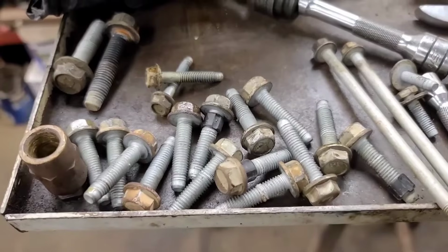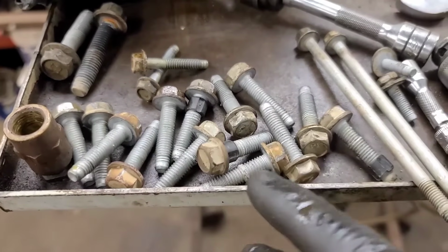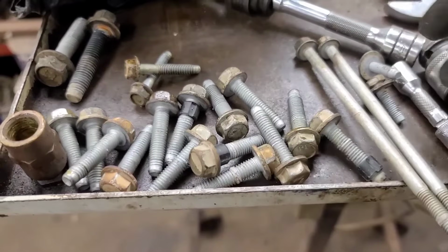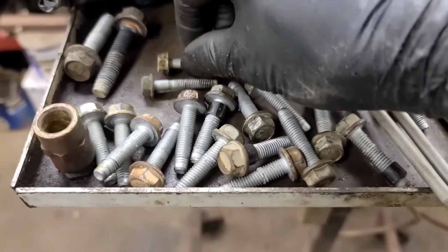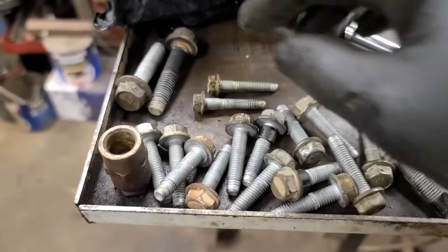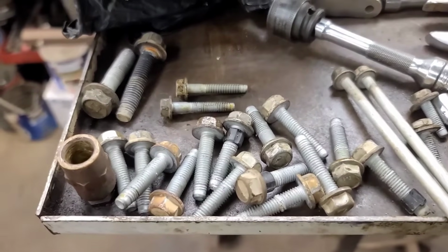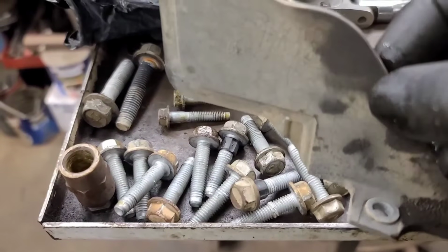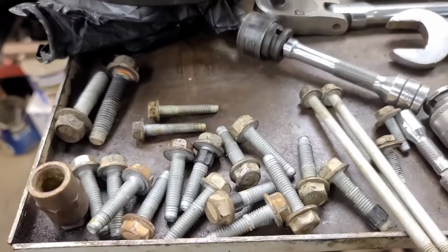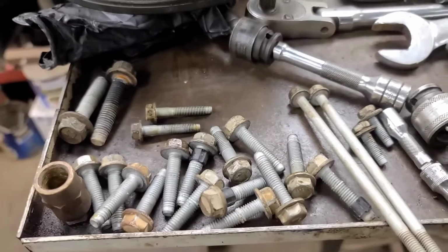It's coming off. So there are 14 8mm bolts, 13mm heads holding the pan on, 2 6mm bolts at the back, vertical, with 10mm heads, and 2 6mm bolts on the oil cooler flange, 2 valve housing bolts that go into the bottom of the oil pan, and a couple of braces. There's the cover on the right or left side, and then the one by the starter. I think you can leave the starter one in there because you can't get it out without taking the starter out. So these 2 little bolts hold the plastic covers on the left and right. Here's the left side cover.